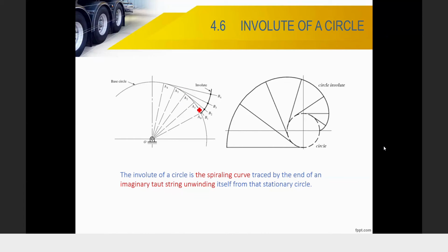I don't want to define it more, the profile, the involute shape of the teeth. There is a way like with a string, where you divide the angle into equal amounts, like dividing by 12. However many divisions you make, they stay the same. At A1, it is perpendicular to your radius, and then you use a compass. You can also do it geometrically, with technical or engineering drawing. Then A2, perpendicular to A2, I don't want to explain. That's how they design it to get the involute of the gear teeth.